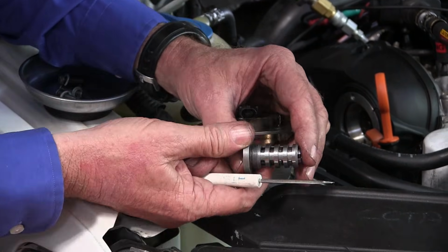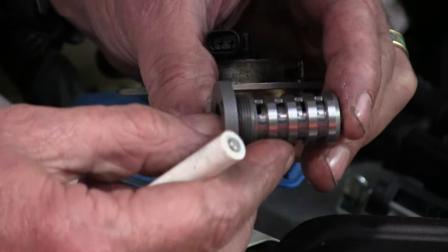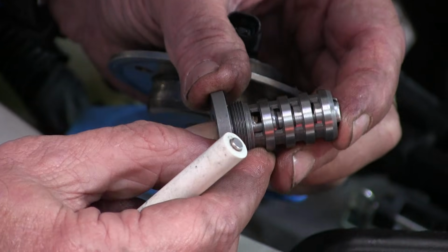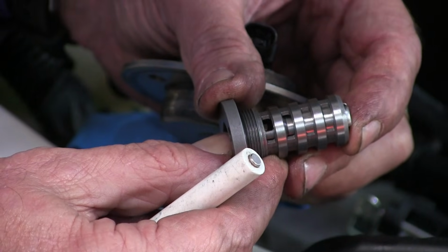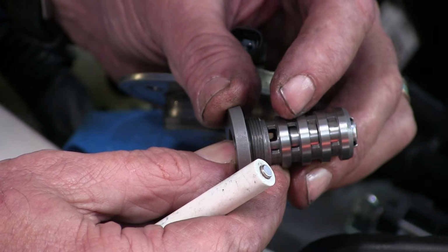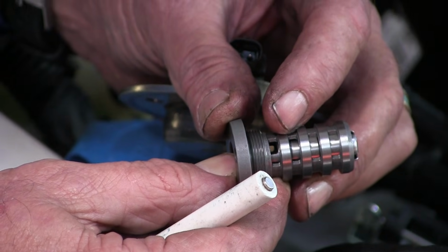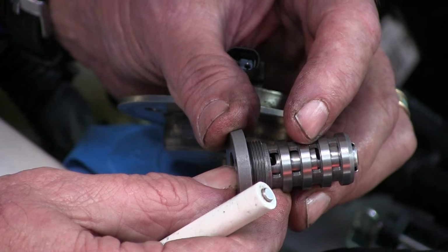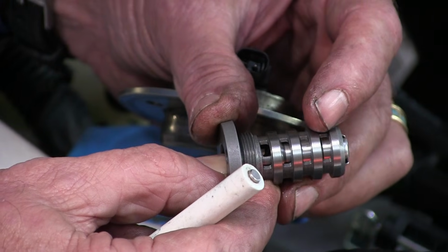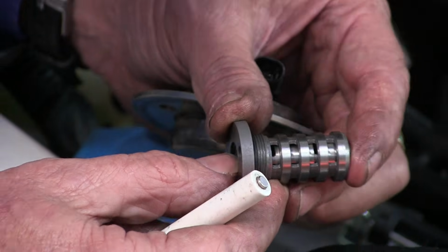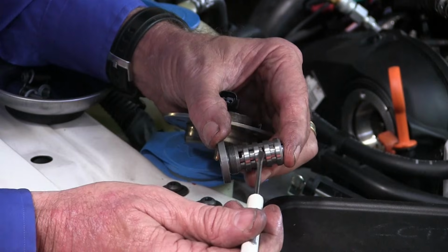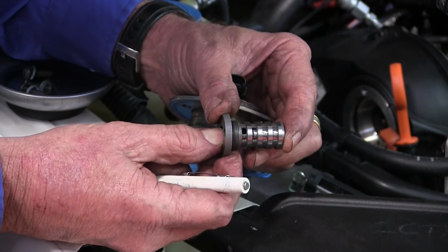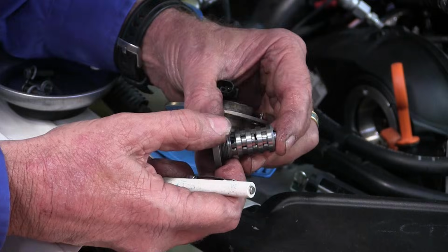When you look at the side of this, this is a spool valve assembly. Do you see how I can see those channels inside there moving? When this moves, I can move the position to where I totally block the oil flow off, where it won't return or apply, and I lock the phaser in a position. When I move it to another position, I put oil on one side of the vane motor. When I move it to the other, I put it on the other side, and then I can lock it. This valve is moving in here, and you can see these guys moving inside that channel, directing my high pressure oil flow to the vane motor so I can phase that camshaft.